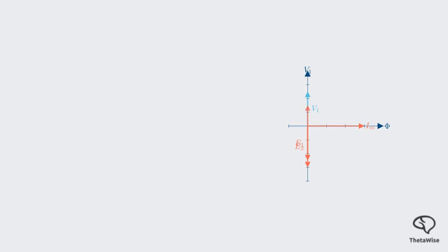Power is real, so I sub C must be in phase with the real component of the voltage, V sub 1. So, we draw I sub C along the positive vertical axis in phase with V sub 1. The no-load current, I sub 0, is the vector sum of the core loss current I sub C and the magnetizing current I sub M. Finally, the angle between the primary voltage V sub 1 and the no-load current I sub 0 is called the no-load phase angle phi sub 0.